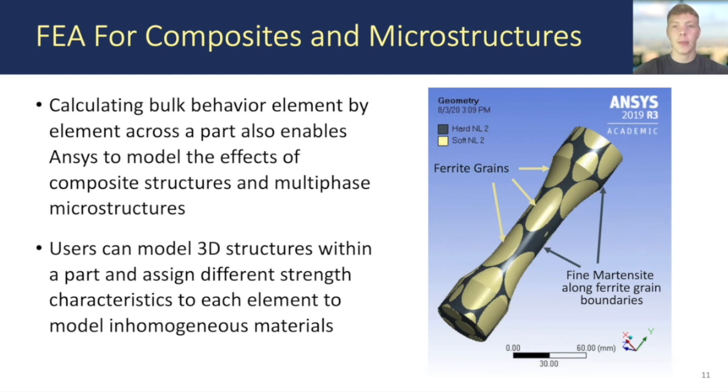Ansys does come with some limitations, though. It is limited in how accurately the user can replicate materials properties within the software and in how detailed of a model it can handle. The more detailed and complicated the model inputs become, the more likely it will be that Ansys fails while trying to generate a simulation. Ansys does have an extensive built-in library of materials and several techniques a user can use to replicate stress-strain plots in the software, but it still relies on tabular values to approximate stress-strain relations for materials. Barring its limitations, Ansys is still a very useful tool in investigating microstructure and composite structures like the one produced in additively manufacturing.